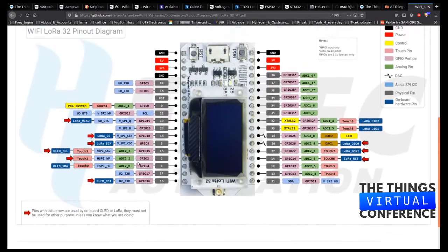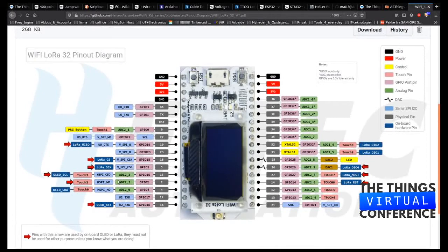And then I can find the SCL, that is the I2C. Where are we? Okay, we will use these two. You see here on the left, it is called 15. It is on the left side, the 5th from below, from the bottom. And here we have the OLED SCL. So it's the clock line that is used for this OLED, the screen display you have here on the top. So this is the clock line, and we have the SDA here for the OLED also.